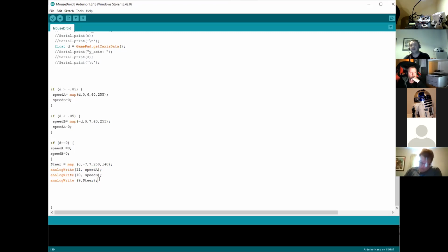Yeah. So it is in there in the data somewhere. It's just a case of finding what particular number you need. And on that mapping, the 60 between 0 and 60, is that your dead zone? Yeah, because what happens with a lot of speed controllers is before they actually start to have enough power to make the motor spin, they'll make that annoying whining noise where it's kicking the coils, but it's not actually turning the motor. So what I can do is I can tweak that dead zone up.